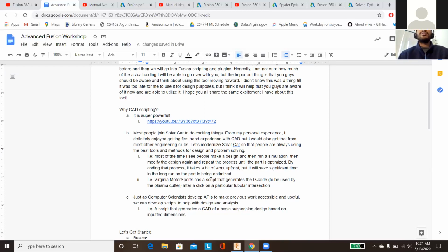You know how hard it is to notch a, well, it's actually not that hard, but notching a tube, right? There's either the manual method where you use a hole saw, and there's this tool, and honestly I was thinking that the hand tool worked out better than the plasma cutter, because with the plasma cutter there's almost like melted sludge that ends up being left behind, and the finish is sometimes an issue. But I guess that's besides the point.